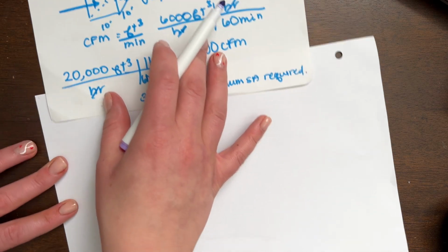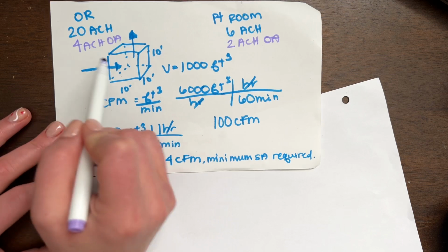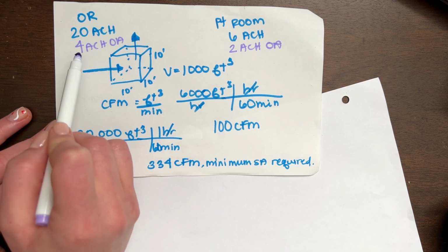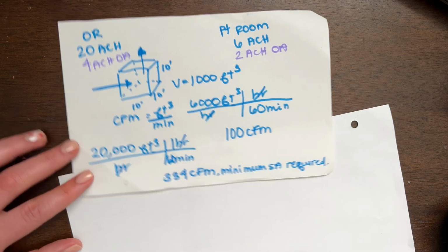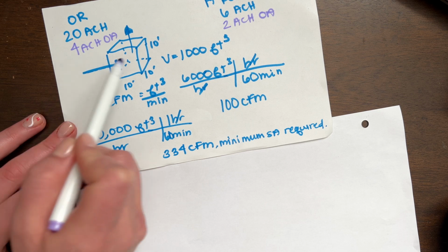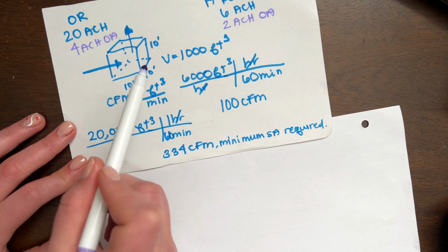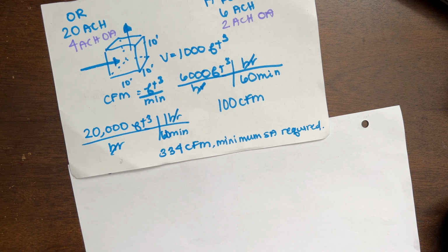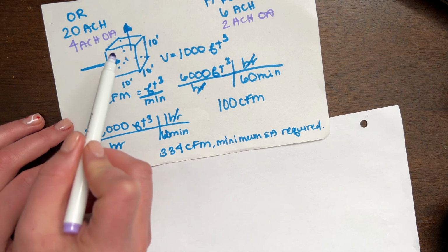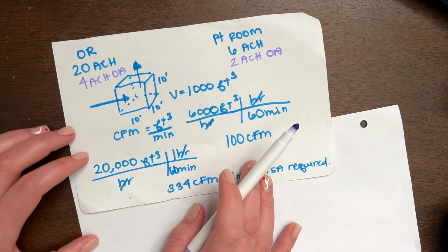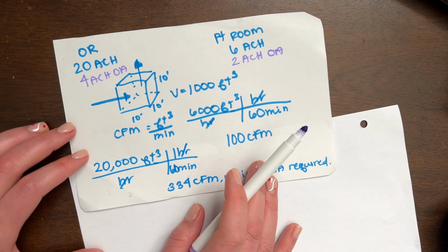What that means is out of this volume of air that's coming in and out, we want a certain percentage of that to be outside air. And right here, if you have a total space where the majority of it is operating rooms, you would want to use these numbers to determine the outside air percentage of your air handling unit design.